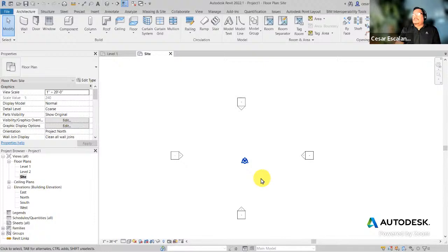For projects where you have all the control, in particular small projects, you can choose to work like this, where the internal origin, the project base point, and the survey point are all exactly in the same spot, and make sure that everybody starts with the same logic. And so it'll be easier.